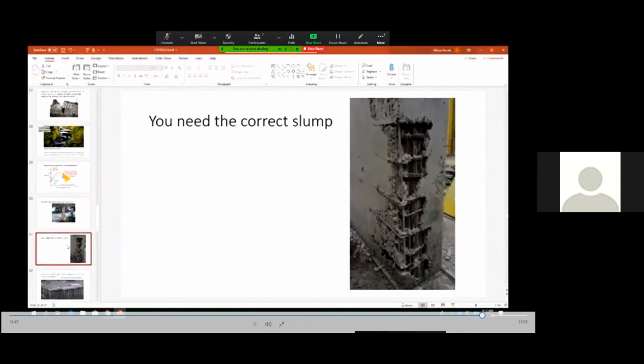This is a bunch of honeycombing. I did a project, one of my very first concrete projects, and I put all this steel in, and then I didn't really think about the laps in the steel, which basically double the area, and I had honeycombs everywhere. It was a nightmare. And so you have to understand that there's two things, right? You can't put so much reinforcing that you can't get the concrete in, but you have to have a slump that will basically move and coat your reinforcing.